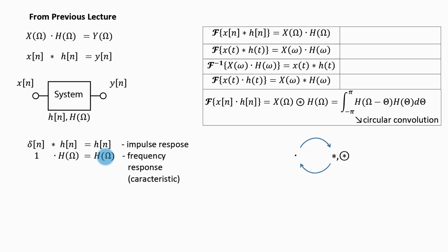Actually, this approach is a tad theoretical. It can work a bit with discrete systems, but with time-continuous systems you may have a small problem generating that infinitely narrow and infinitely tall Dirac delta pulse. So especially with time-continuous systems, we usually measure the frequency characteristic by other means. But at minimum, you should understand the principle of getting the impulse response and frequency characteristic.